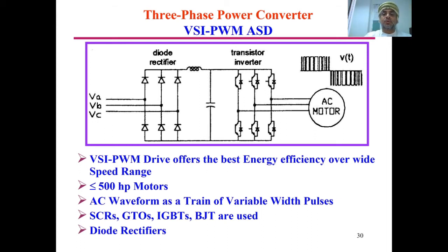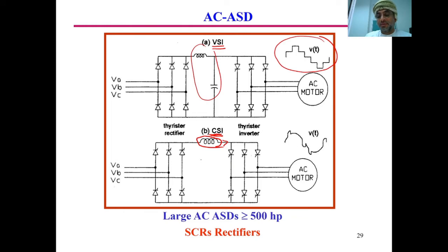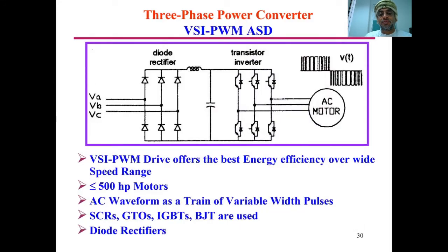We can also use what we call an inverter based on PWM, pulse width modulation. Those inverters convert the DC to variable AC, and the switches will be switched on by using pulse width modulation. And again, what is the advantage of those? That will reduce the amount of the harmonics compared with the 6 pulse or with the 12 pulse.